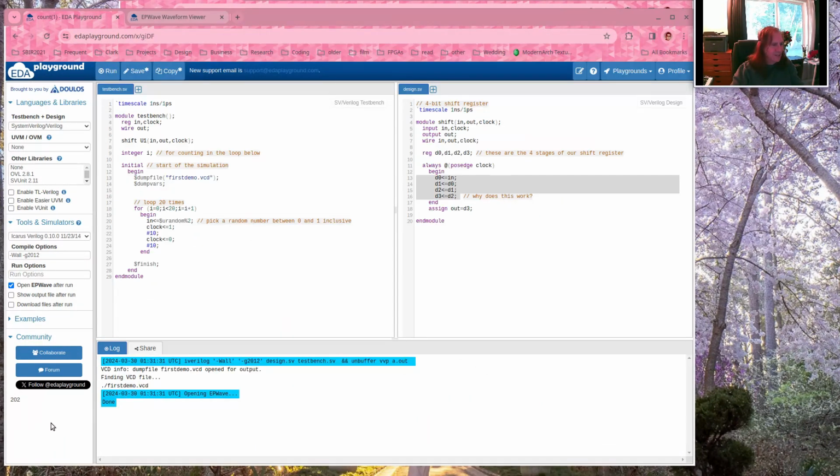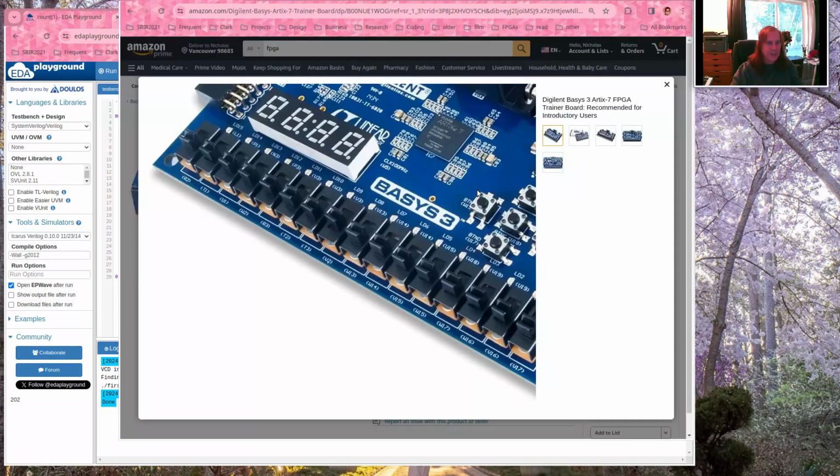And your Verilog tool will figure out for a particular type of FPGA how to program it to implement a circuit that you design in Verilog. And so you can actually create a physical piece of hardware that performs some action, like being a 4-bit counter, or being an arithmetic unit, or something that plays a video game, or whatever it is you like.